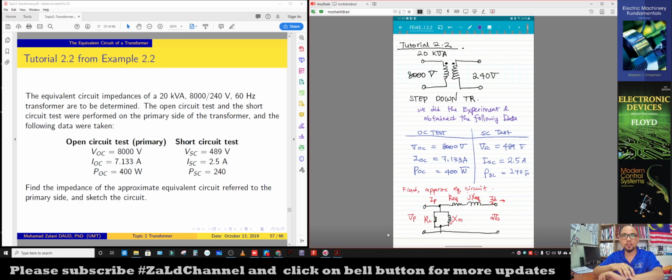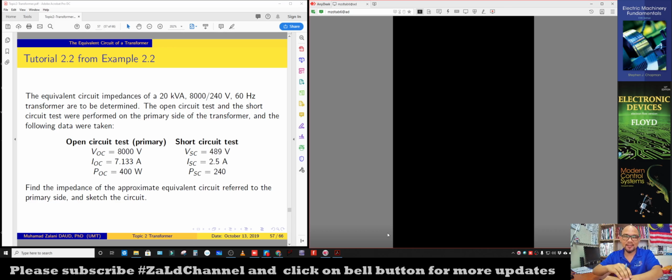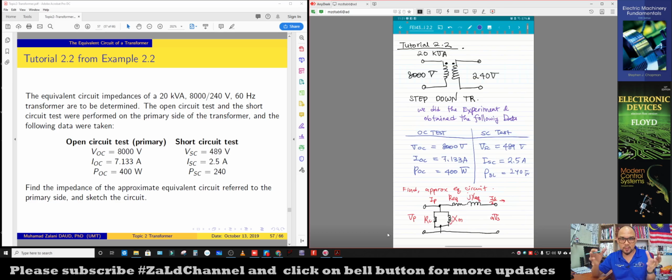Today in this video, I'm going to show you how to solve tutorial 2.2, which is related to transformers. Actually, in this topic 2, we have reached up to the transformer open circuit test and also short circuit test to determine the values of the components so that we can do the equivalent circuit of the transformer. Right, so we want to represent the actual transformer, for example, in terms of an equivalent circuit. So what we do is the open circuit test and also the short circuit test.